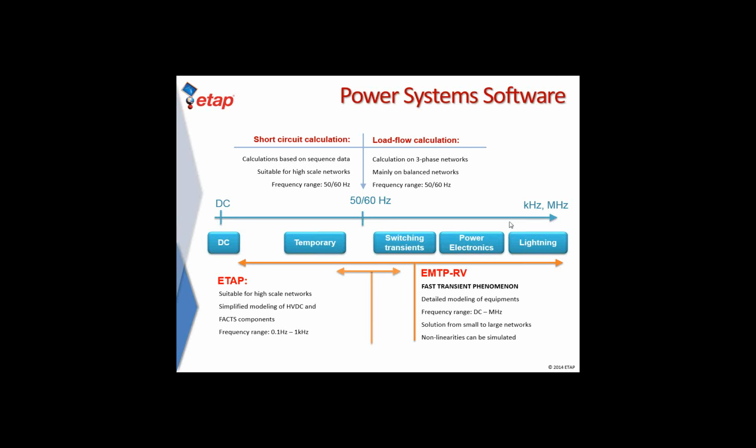I also want to simulate power electronics, and I need to have very good physical and detailed model of the power electronics. For instance, we have absolutely extremely detailed model of PV converters and wind converters and HVDC converters that can actually model and simulate all the details that you can have inside such a converters. Finally, we also want to simulate lightning stroke and to see the effect of a lightning strike on the power system.